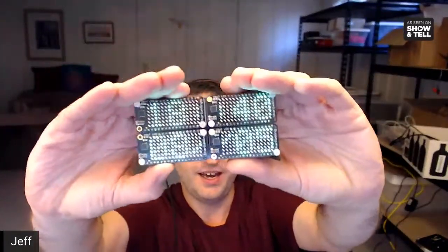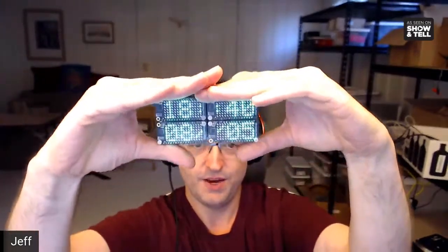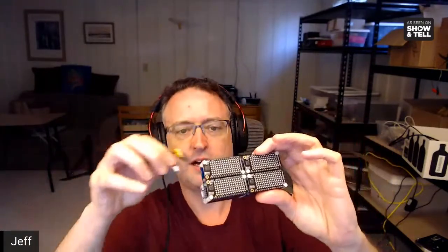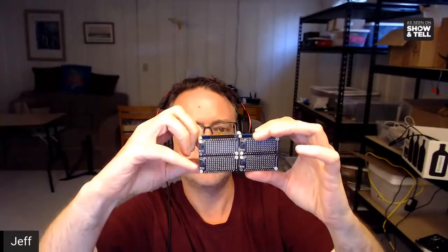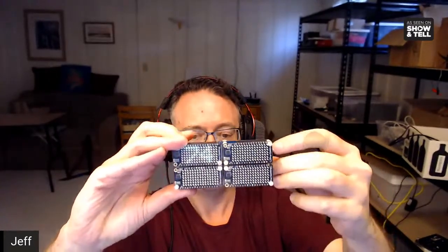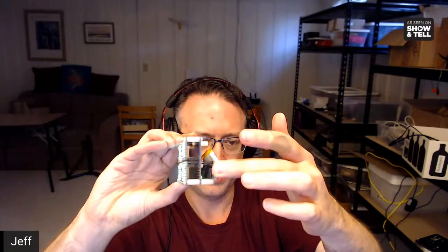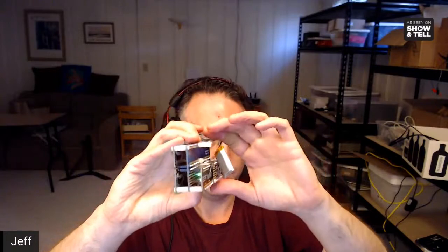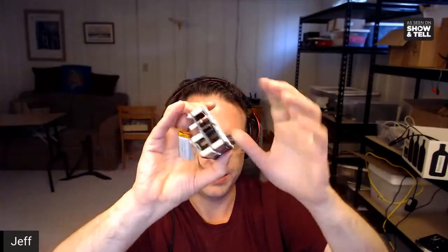I've come on Show and Tell a couple of times talking about things related to timekeeping, and today I'm ready to show the clock I've been working on, which is this little guy. Of course the lighting makes it hard to see the LEDs, but anyway, we're local time 1840 and the date 0805. So basically I want a clock that I don't have to mess with, I don't have to set, unless the law changes or I move to a different state. So we're running off of a battery, but normally you'd be plugged in on USB. But because it has the real-time clock, if you lose the battery power of the battery that runs the displays, it will reset and you get your time back because it's got the real-time clock module, which you can't really see down there, which is carefully calibrated to within about a second per month. It adjusts for daylight saving time, and I guess that's about all it has to adjust for.